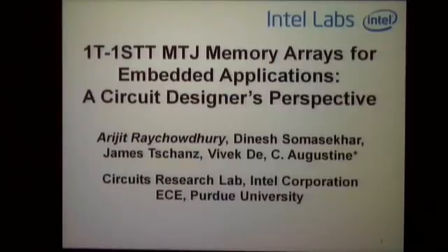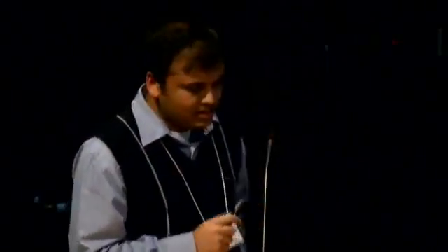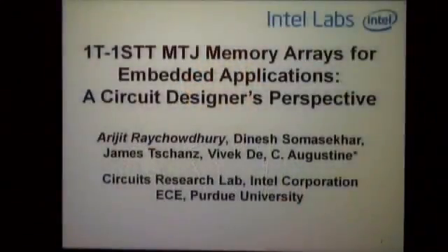So the title of my talk is the 1T1 STT-MTJ memory array for embedded applications. This is kind of different from most of the non-volatile memory forums and application spaces that we look at. It's essentially off-chip memory that we talk about, non-volatile flash or even magnetic memory. So I'm going to take a stab at looking at something which, apart from Intel, many other companies, industry and academia alike, are looking at, which is essentially to study this kind of memories for embedded applications, for very high density on-chip memory. And I'll present some of our thoughts from a circuit designer's perspective.